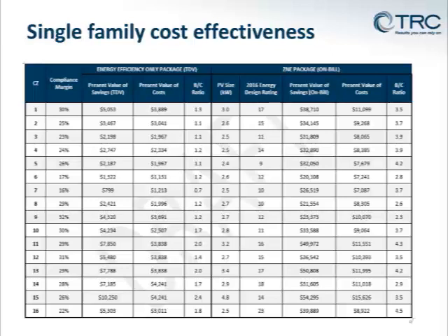Which slide are we on there? Slide 8. Okay. So the PV size is kind of in the middle of that slide in terms of kW. And then we look at, punch in the CVEC res hourly outputs into our utility bill calculators, which we have painstakingly made sure that the on-peak, off-peak, mid-peak, non-bypassable charges, baseline credits, all this other stuff is modeled as accurately as we can.